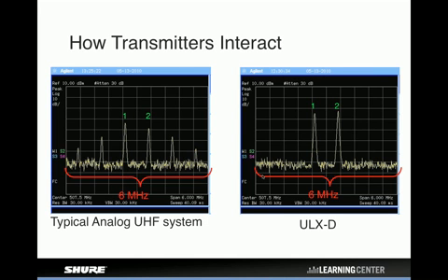So now talking about intermodulation, primarily in wireless microphone systems, we're mainly concerned with the intermodulation products that are produced when multiple transmitters are operating in relatively close proximity to one another. If we look at the spectrum analyzer screen capture on the left here, we're looking at a 6 megahertz window. Only the two peaks labeled 1 and 2 are actual wireless mic transmitters on the air. The other peaks that you see, which of course are frequencies that you would need to avoid, are intermodulation products that are created by these two transmitters when they get close enough to essentially pick each other up.